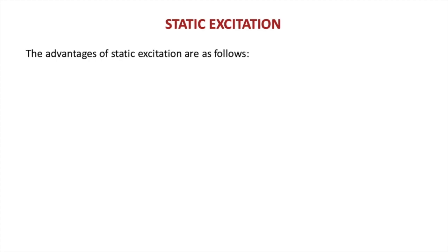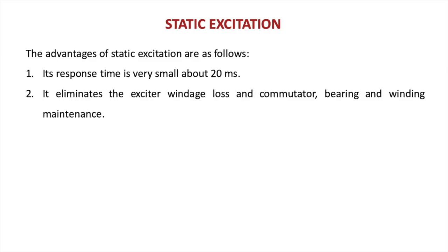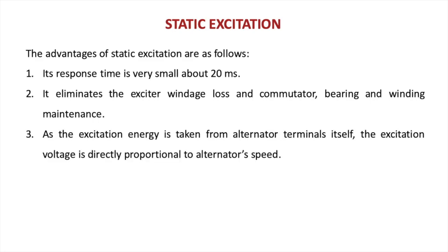What are the advantages of the static excitation? This static excitation has the advantage in its response time, that is very small, about 20 milliseconds. It eliminates the exciter winding loss and commutator, bearing and winding maintenance. As the excitation energy is taken from the alternator terminal itself, the excitation voltage is directly proportional to the alternator's speed. This improves the overall performance of the system.